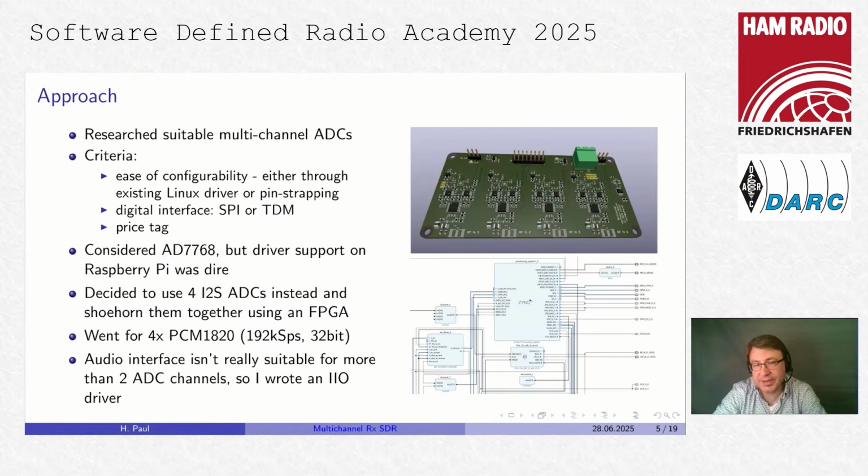This is what you see in the top right figure. This is a rendering of the PCB, and basically it's 4 times the QDX receiver, and the 4 switching mixers are driven by the same clock synthesizer, so means we get a perfectly coherent system. The LO is synchronous as well as the sample clock as well.